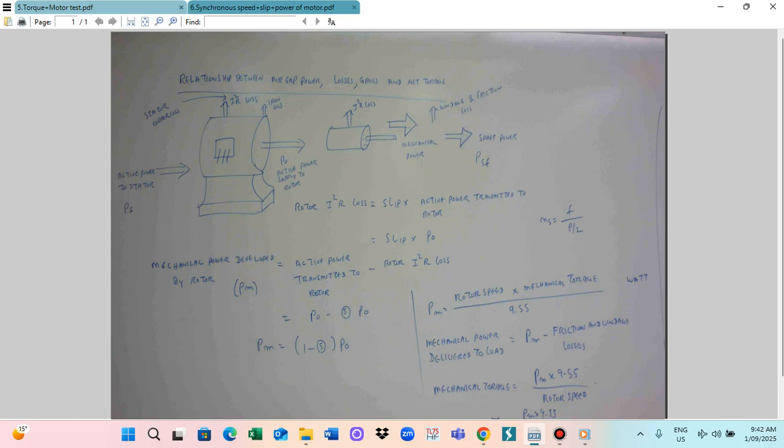Those fluxes pass through the rotor bar, and so a voltage is induced in the rotor bar. At the same time, current is also induced in the rotor bar. The stator magnetizing flux and the magnetic flux produced by the rotor bar current interact, and that rotates the motor.